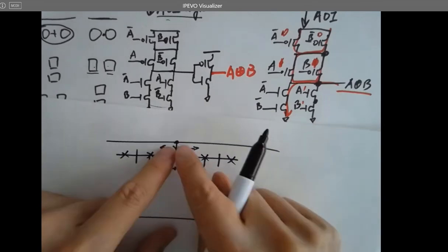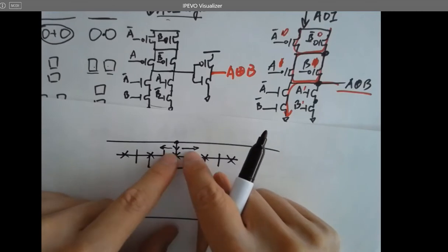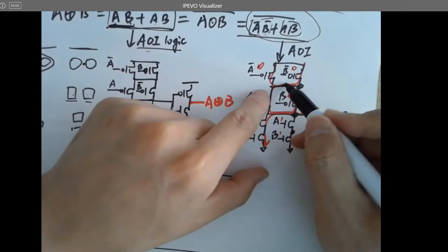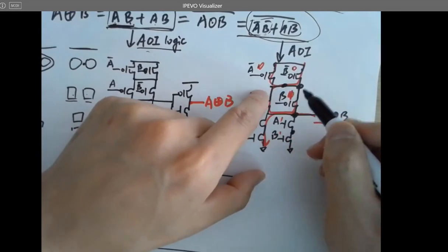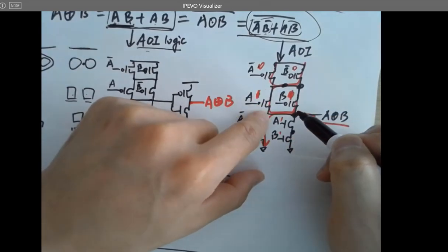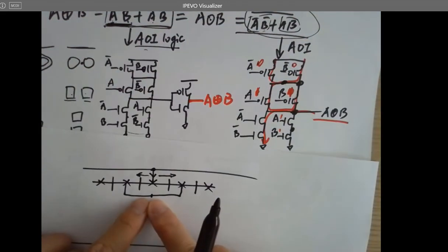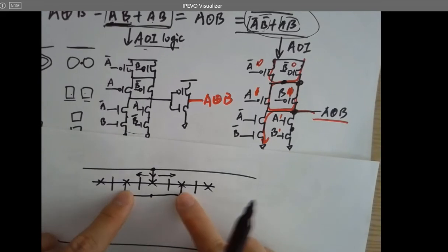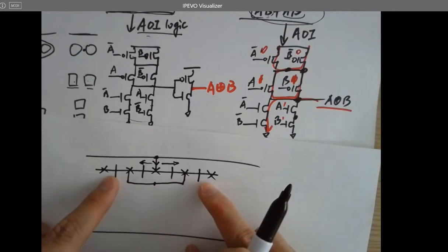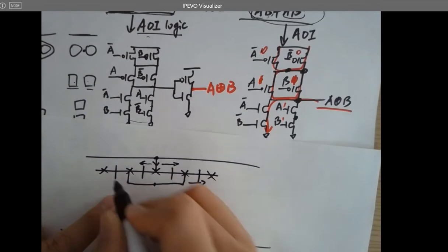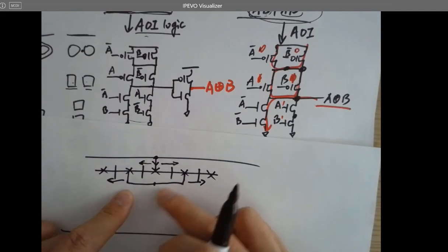And after this current is split into two branches and reaches this one point, it's split again into two branches to flow through two other PMOSes. So that's one point. It's naturally just going through these two PMOSes, because there's no other place to go, right? So it's going to flow like this and flow like this. I mean the current, it's going to flow in these two ways.